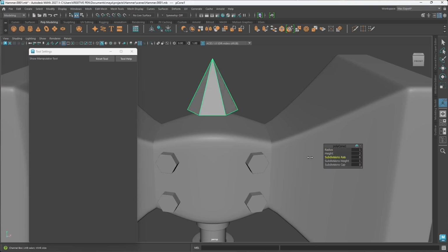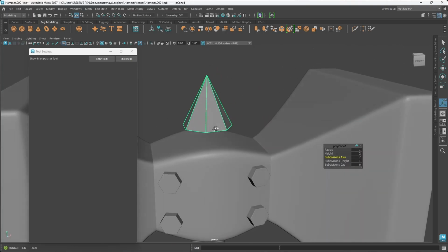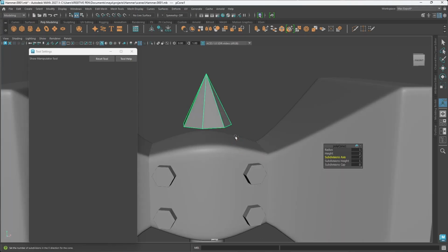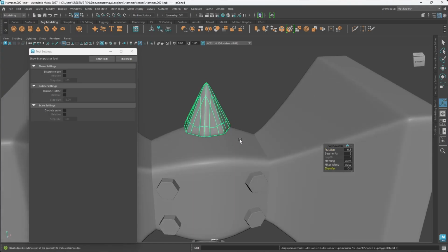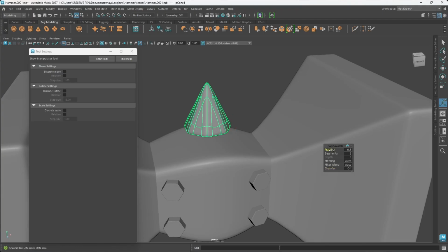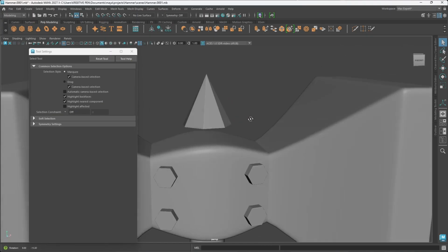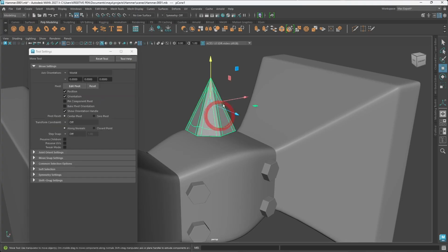Now we're going to do what I don't actually like. So we have 7. My 7 works, we can just work with 7. So we hit on Control B to bevel, turn off the chamfer, hit on 3 to go into the subdivision mode, then reduce the fraction to make this sharp. Yeah, this is exactly what I don't want, but it added this kind of nice hard edge. I don't like that, but I can work with that.